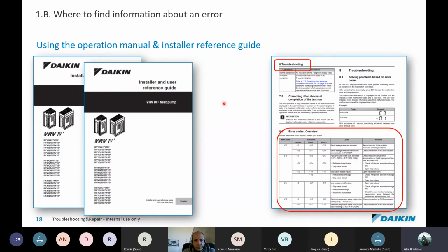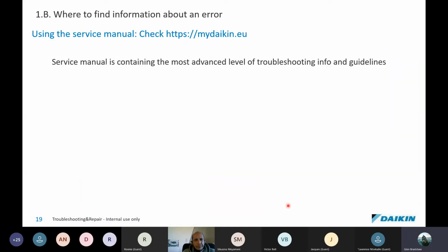I'm just going to recommend that, because I get asked this question often, I'm going to just put it out there, that by South African legislation, we are only allowed a 5% decrease or increase, depending on the mode, in temperature difference between the condenser and the indoor unit. So just keep that in mind when you're selecting Armaflex. All right. This gives you an idea of what the fault finding or the troubleshooting side of that manual looks like, and how it's laid out. And it has some of the system errors in there.